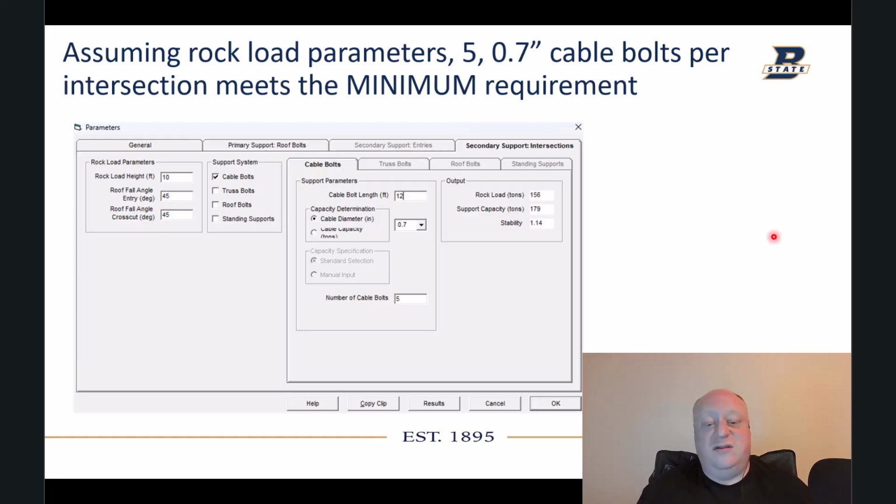It's a relatively few number of cases where it didn't work, and then you need the 6 bolts, which I said is most common now probably, and what I would recommend. I would add 6 bolts here instead of 5, but I'm just showing that this does meet a minimum guideline on what you might need. I say requirement, but this is not a requirement.